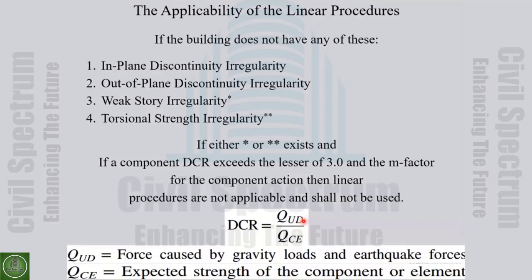So by design, by implementing design articles, we try to concentrate the damages, for example, in bending, if the bending in that element is more ductile. For concrete, usually we are scared of shear, so we don't count shear as a ductile behavior, or torsion or axial behavior.